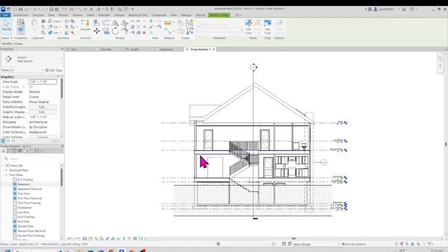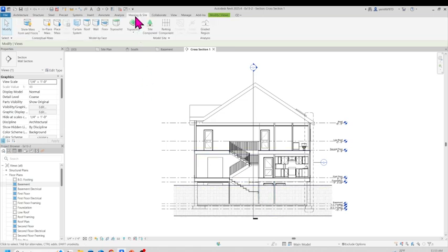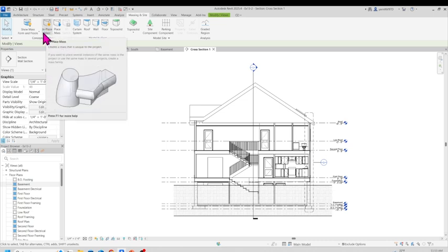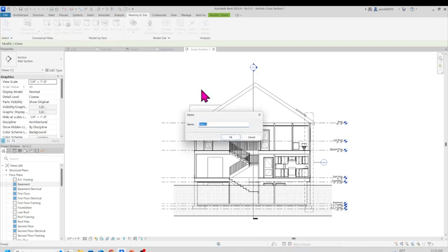So to do this, we're going to go to the massing site again. From there, go right here where it says In-Place Mass. Make sure you click In-Place Mass, not Place Mass. Click that one, and then a window opens, showing massing enabled. Revit has enabled the show mass model. Click close. The reason I don't have it is that this is the second time I'm doing this. And name your mass. This is a basement, so we're going to call it basement area, and click OK.